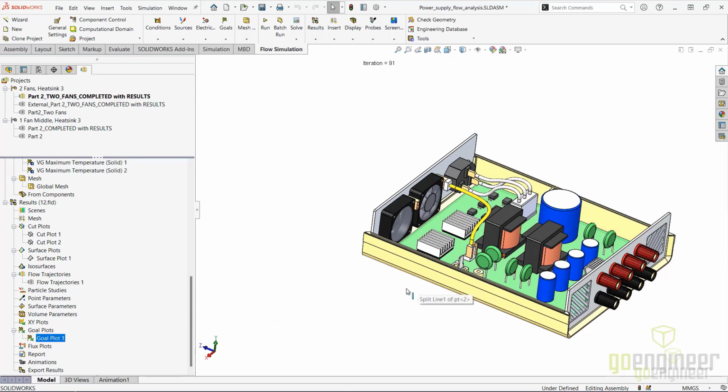So let's take a step back and look at the bigger picture here. We've been running these projects by calculating the internal volume of the box and idealizing the external environment so far. Let's see what happens if we introduce a bit of actual air fluid medium around the box. We've been assuming that most of the heat transfer happens by the air entering the two vents and out of the fan definition regions, right? But now let's explore if the natural convection of the actual electronics housing can help with the heat transfer in those IC areas.